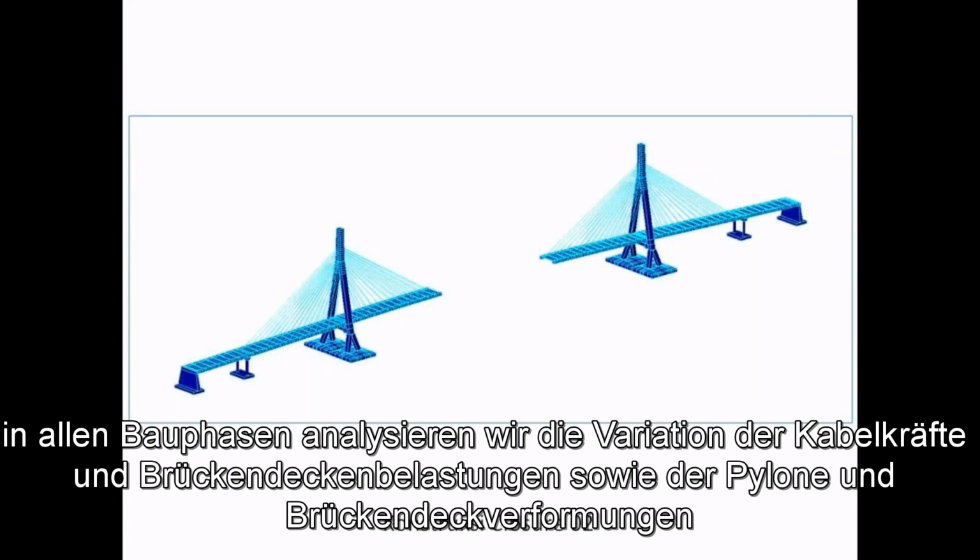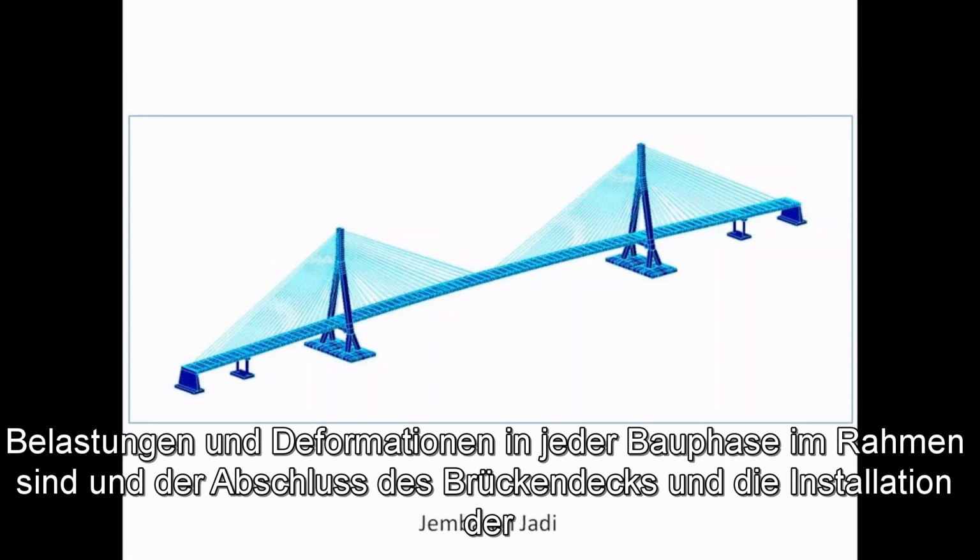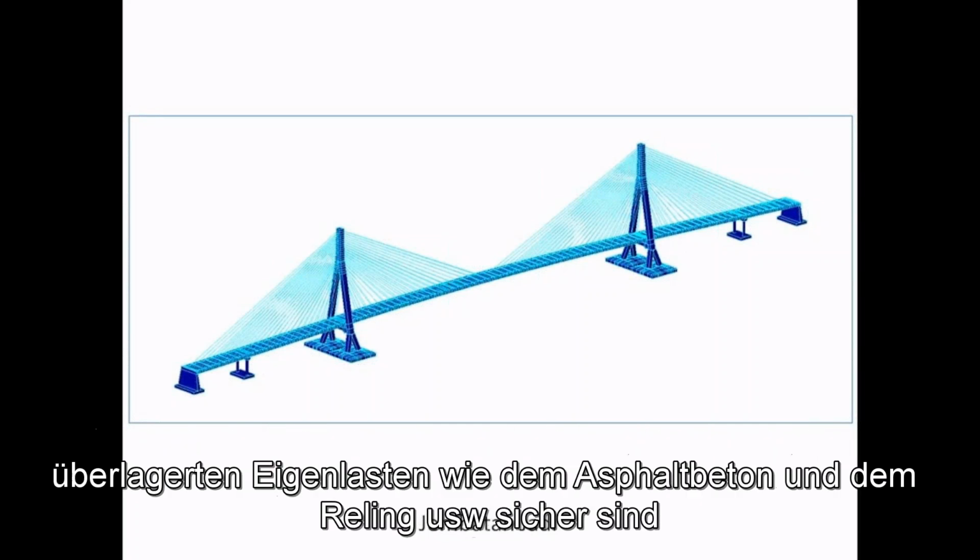In all construction stages, we analyze the variations of cable forces, bridge deck stresses, as well as the pylon and bridge deck's deformation under all construction loads, including the traveler's loads, in order to make sure that all stresses and deformations are safe in every stage of the construction process until closure of the bridge deck and installation of the superimposed dead load such as asphalt, concrete, railing, etc.